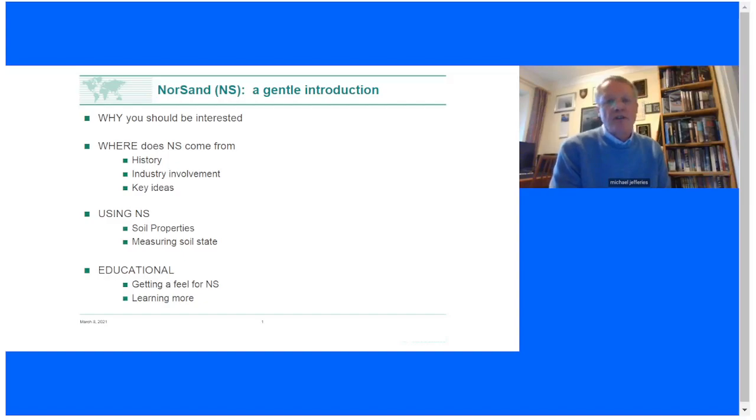I will then move on to where Norsand comes from. This is perhaps what you might be more expecting from the title of the talk, but I'll go through the history and why it came out of industry rather than our universities. Having done that, I will then go on to using Norsand. Remember, it's garbage in, garbage out. So you can use Norsand by firing up PLAXIS and saying, yeah, I want to use this block of soil as Norsand. But we need to think about the properties you assign and the soil state you assign. So I want to get into a little bit about how you use it and how you use it properly.